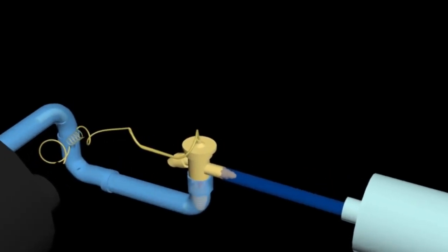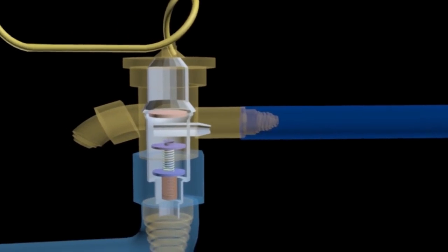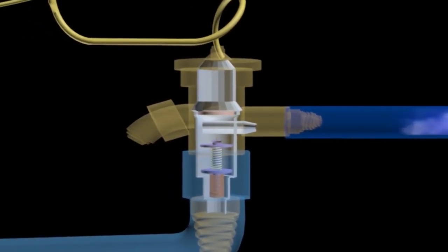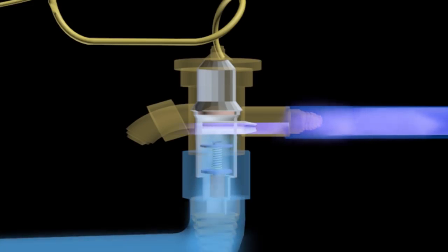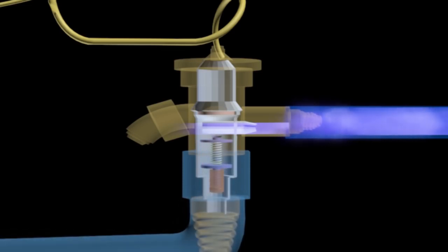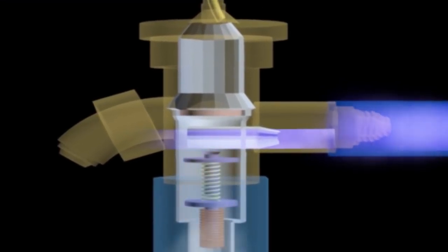Expansion valve. The expansion valve serves to reduce the pressure and control the flow of refrigerant going into the evaporator. When the pressure of the refrigerant has declined drastically, the temperature will drop dramatically, which is lower than the chilled water temperature. In a centralized system, the TXV thermal expansion valve type of expansion device is used.